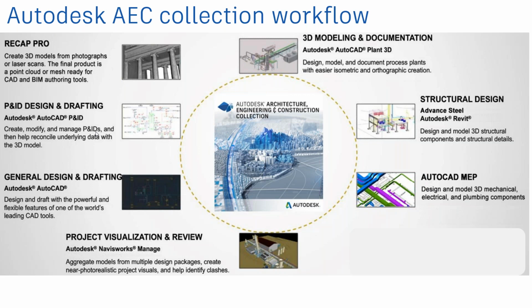When I differentiate between Revit and Advanced Steel, if it is a concrete detailing project, you could transfer information between Plant 3D and Revit, model out the concrete elements inside Revit, detail out that information in Revit, and generate your sectional and elevational details, plan details, as well as the BBS schedules which you require for your structural concrete components.